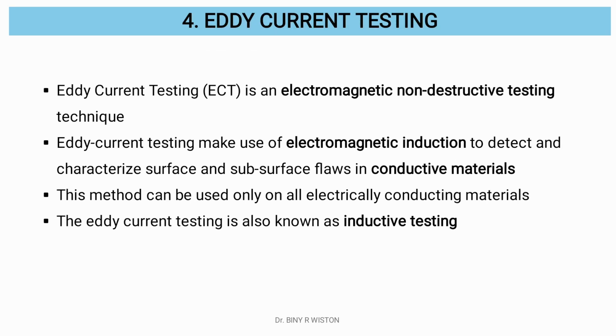Eddy current testing is an electromagnetic non-destructive testing technique which is primarily used only on electrically conducting materials. It makes use of electromagnetic induction to detect and characterize the surface and subsurface flaws in conductive materials. The eddy current testing is also known as inductive testing.